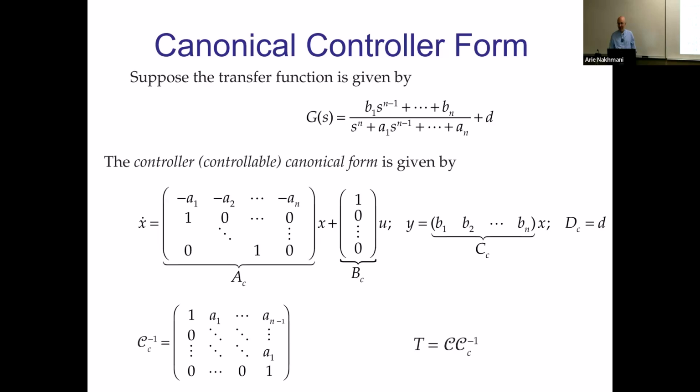Yes, okay, it will cancel out in the computation, and you're getting into a more deep and very interesting question: what effect B will have on the system in general, and what effect C will have on the system in general. Because if you're thinking about state space and design of the controllers for state space, C is not involved at all, which means regardless of what coefficients you have here for zeros, it will not change anything about your design of the controller.